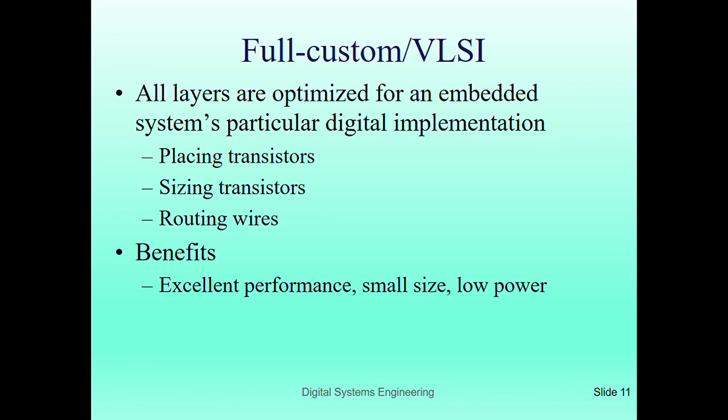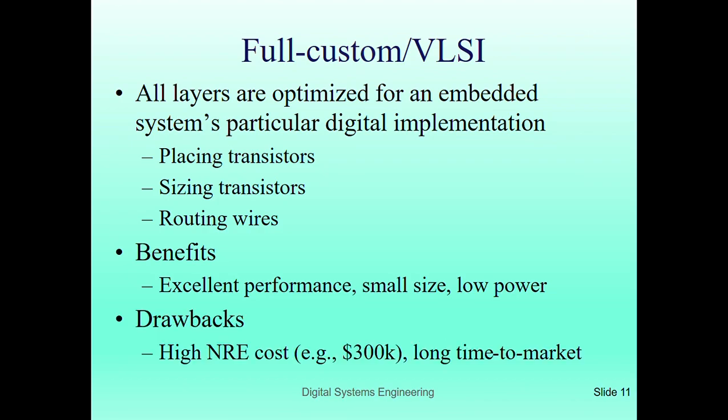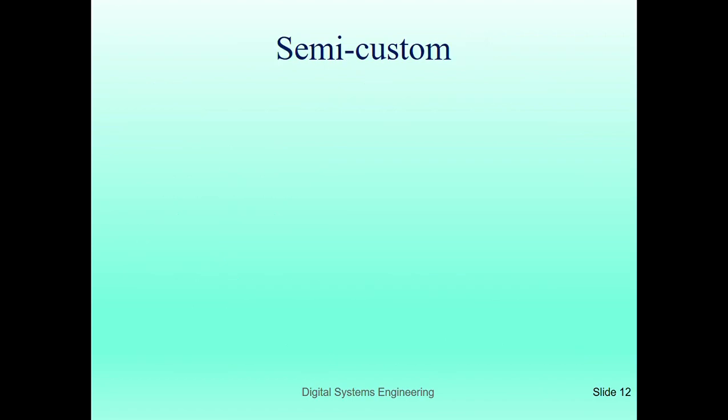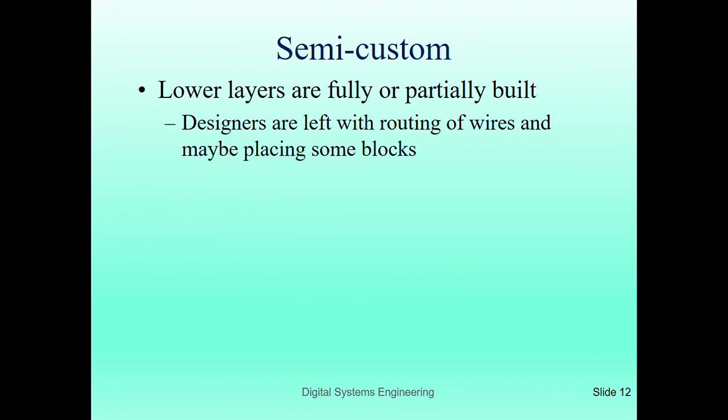There are some benefits of full custom design: excellent performance, smaller size, and low power dissipation. Similarly, they have some drawbacks, like high NRE cost, or non-recurring engineering cost. This is the first-time design cost, which is around 300,000 US dollars, and they have a long time to market. Next, the semi-custom IC designs.